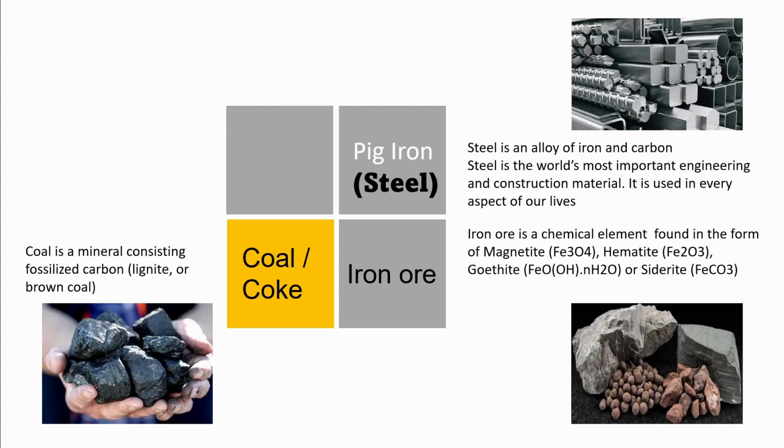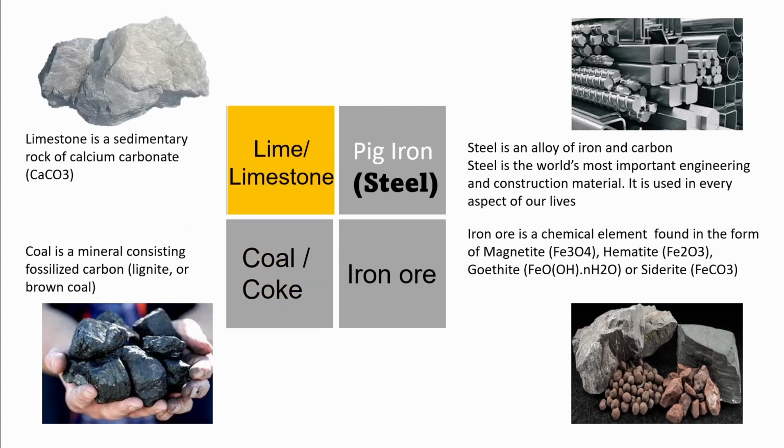And with just these two, it is possible? No, because there needs to be an element which will take care that the heat is not getting lost, or there is a cover. We need to have a cover, that is limestone. So basically, the limestone is used as a cover, which will create a slag in the form of a layer on the blast furnace, which will make sure that when the temperature of the iron ore gets increased above 1500 degrees Celsius and close to about 1700 degrees plus, it starts becoming droplets of iron and starts getting accumulated in the bottom of the blast furnace.